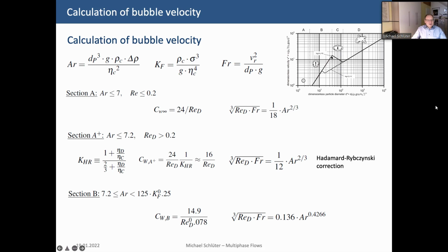And you also remember that the bubble rising velocities are changing. They are first rising. If the bubble is spherical, then we have a shift in the shape of the bubble to ellipsoidal bubbles. The velocity decreases, and then with further increasing diameter, we come to formless shapes and constant rising velocity again. So please keep this slope, this line, in mind, how it looks, to be able to draw the dependency of bubble velocity on bubble diameter. And please don't forget, this is a double logarithmic scale here, yeah? This is double logarithmic.